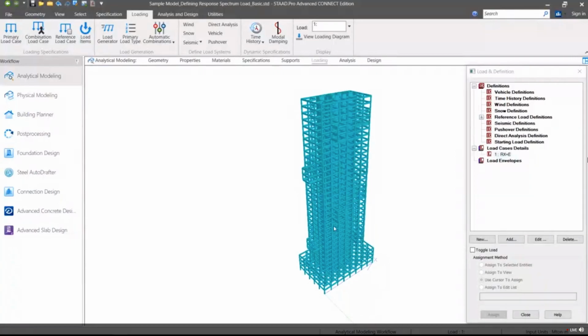First load combination should combine load case 1, which is the response spectral load from X direction with positive accidental eccentricity value, and 30% of load 6, which is no torsion load from Z direction. Second combination is the load case 1 and 30% load case 6 from negative direction. So minus 0.3 is the combination factor.